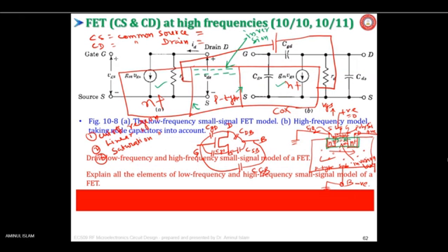Okay, concentrate here on this junction. Is this PN junction forward biased or reverse biased? Tell me. Yes, sir, reverse biased. So when reverse biased, can electrons or current flow? It is reverse biased because the negative terminal is connected here and the positive terminal is on this side, so electrons will be moving in this way.